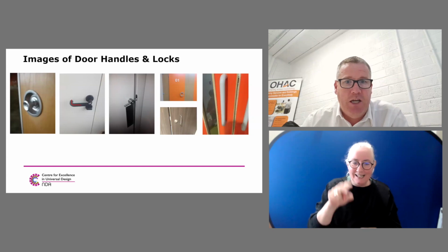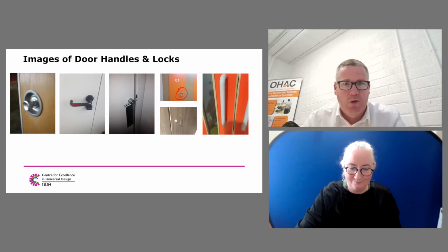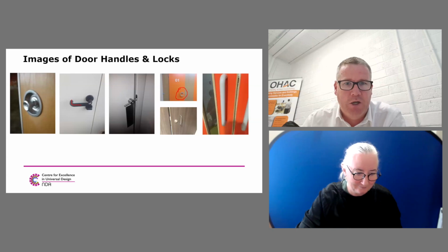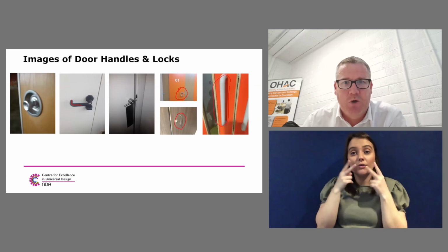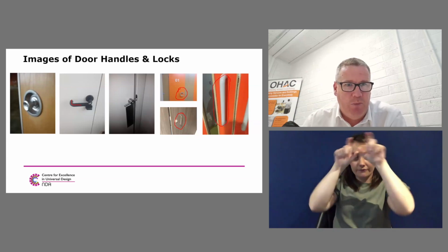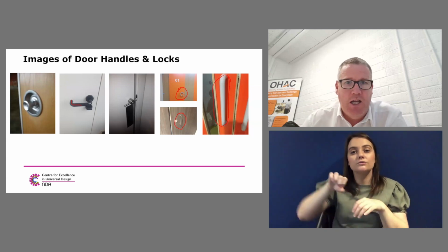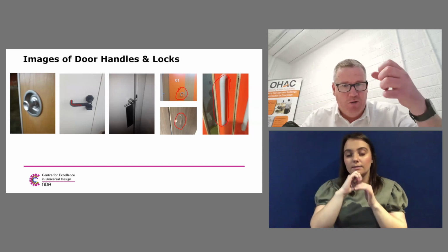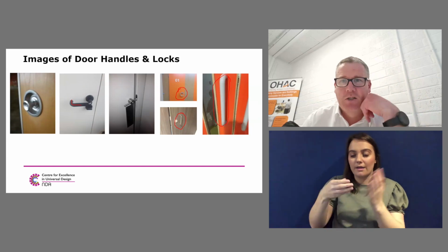Again, on an ambulant disabled door, make sure that the door opens outward, so that you have pull handles on the outward opening door, and then good visual contrast on the pull handles between the door and the frame of the glass and stuff like that. So again, keep an eye on that. But things like door locks, things like returns on the door handles, easy to grip, so that the profile, the diameter of the handle, isn't too thick or too thin and so on.